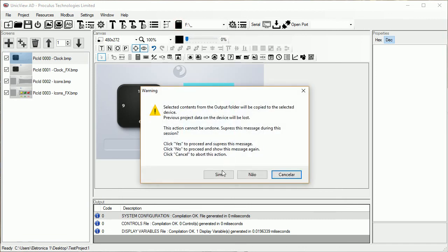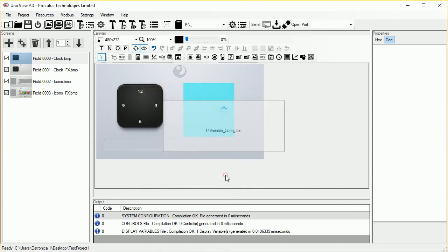After the copy process is complete, you can remove the SD card and insert it into the LCM. If you are using a direct USB device, the files are already updated into the LCM. Notice that direct USB cable are plugged directly into the LCM, and no serial adapter is used.